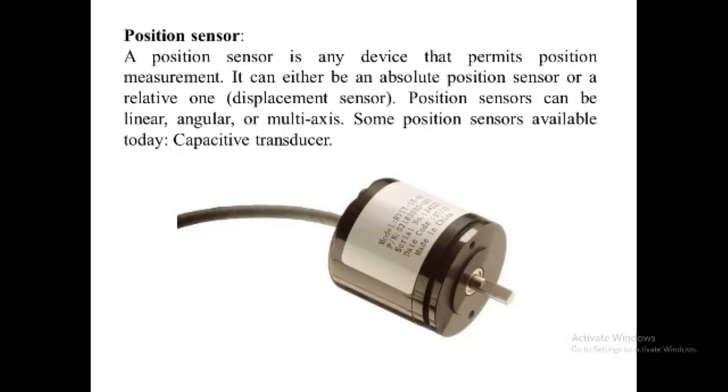Advantages of the LVDT compared to the resistive potentiometer are that its linearity, that is, its voltage output to displacement, is excellent, with very good accuracy, good resolution, high sensitivity, as well as frictionless operation. They can also be sealed for use in harsh environments.